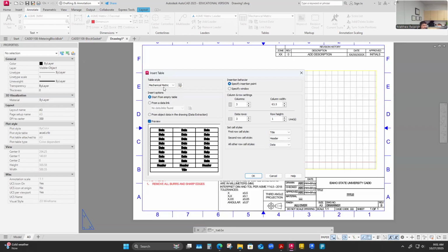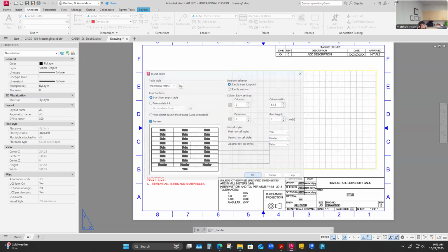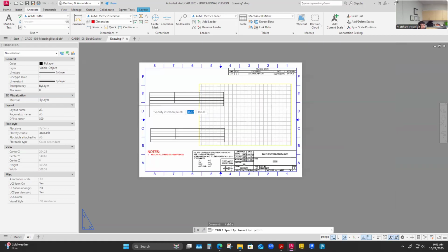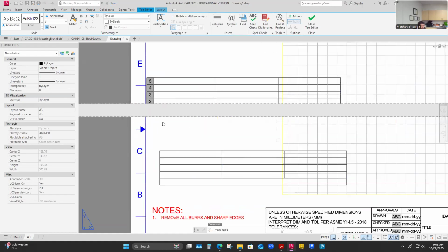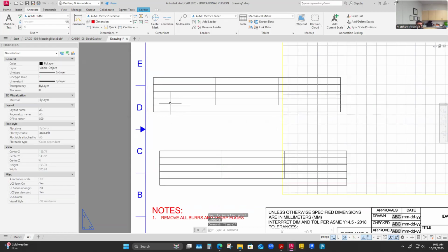But it's going to follow that style, which means it's going to have that text style inside and any of the other data that I would have changed, whether you flipped it the other way or not. Of course I could name this stuff, but anyway, I would just say I'm going to drop this table on my actual sheet. So I'm not dropping it in a viewport. I'm actually on my sheet where I put my title block and I would drop it. And then I could start modifying it individually.